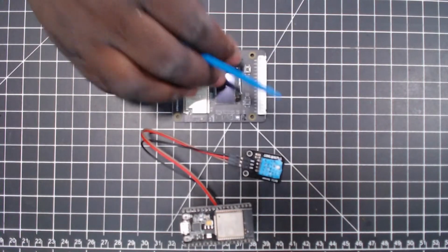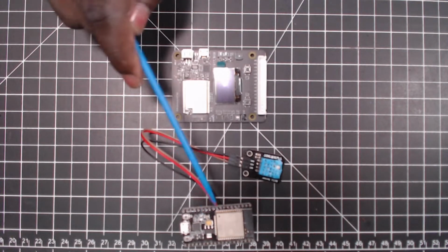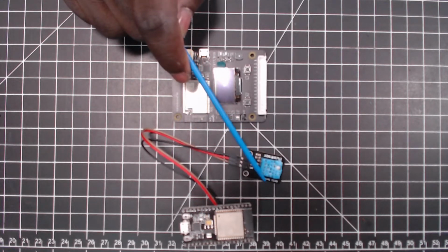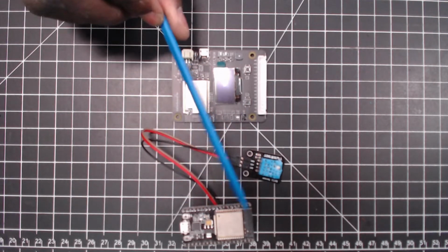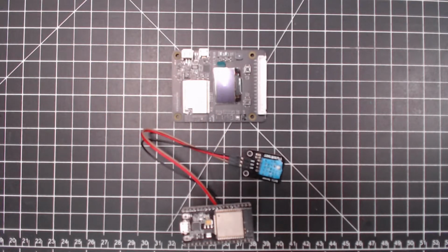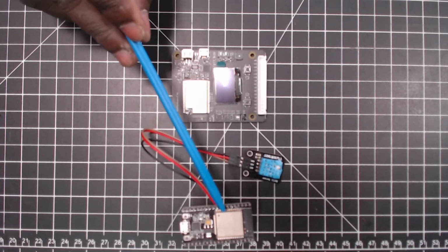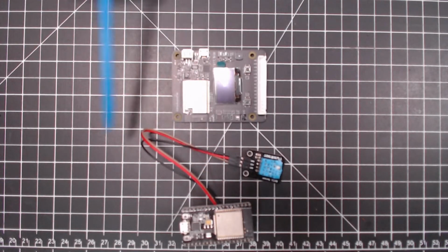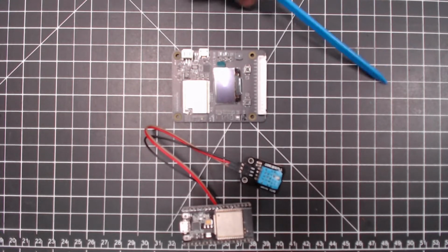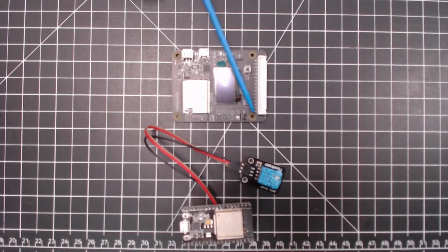Okay, so now take a look at this. You see this ESP32, I've only connected it to a temperature humidity sensor right here. Now, if I wanted to connect another sensor and send the data, I'd have to find a way to connect it, because this one doesn't have Grove sensors. So I'd be doing something like this with a jumper cable, connecting this DHT11 temperature and humidity sensor. Now think about that. This one has a temperature humidity sensor, a barometer, an ambient light sensor. It has everything in one.